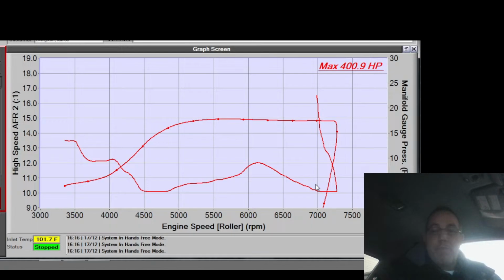Well, what happens when I have a cylinder that's already retained a bunch of heat and I have fuel that is relatively low octane for the amount of load that it's carrying? Well, now I have this really hot spot in the middle of the cylinder. Now, detonation is typically, or is, a secondary combustion event that is ignited somewhere in the cylinder near peak cylinder pressure, so typically 20 degrees or so after top dead center.